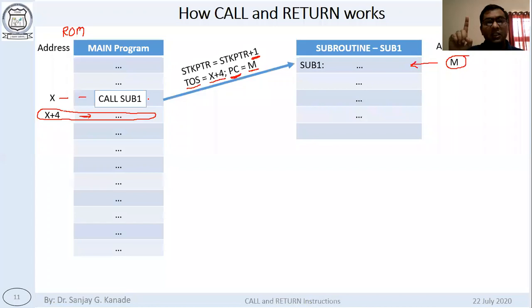Stack pointer gets incremented, then the address of the instruction which is written next to the call is loaded into the stack using this, and then program counter is loaded with M. This M is in this case the address of the subroutine, the address of the first instruction of the subroutine.